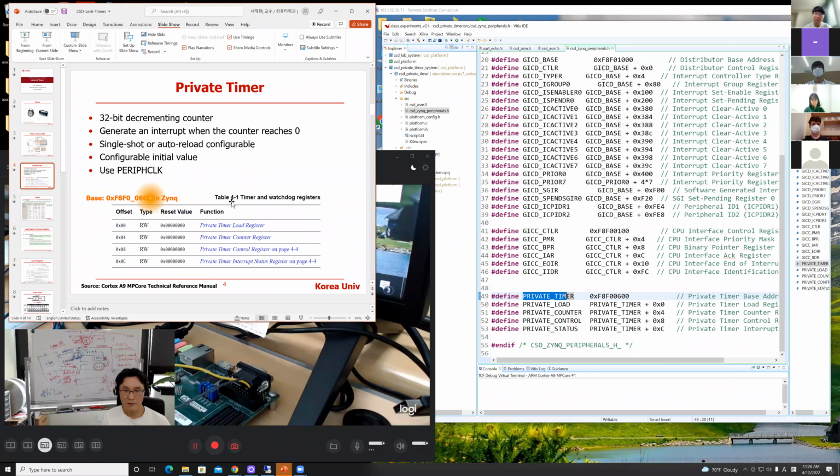And this code is reading from the counter register. Let me show you. The counter register is counting down, right? So when you read from the register, you would see the numbers decrementing. Same location, R0, R0, R0. So the number loaded here will be smaller, getting smaller because it is decrementing.